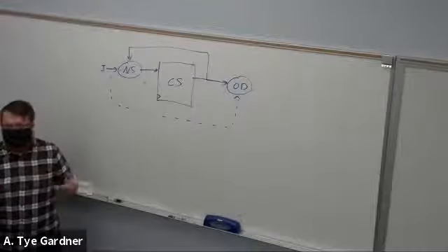So if I'm using a process and want to stay in combinational logic, I just take all of the possible inputs and add them to the sensitivity list. So if I add I and however many bits of current state, that basically makes this combinational because it will react any time any of those inputs change.